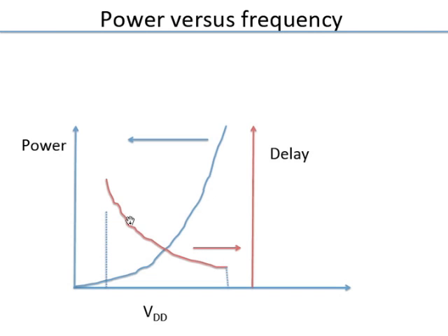Now if you look at the delay out here, there is a minimum voltage at which the circuit will work. We discussed that a couple of lectures ago. There is a minimum voltage, and theoretically the minimum voltage is pretty small, right? We said it's 2 times thermal voltage times log of 1 plus n. That turns out to be about 48, 50 millivolts or something, and people are able to also work down to, in silicon in the laboratory, about 100 millivolts, and people report chips in literature at 180 millivolts and so on. So 200 millivolts, if nothing else, is reasonable to expect.